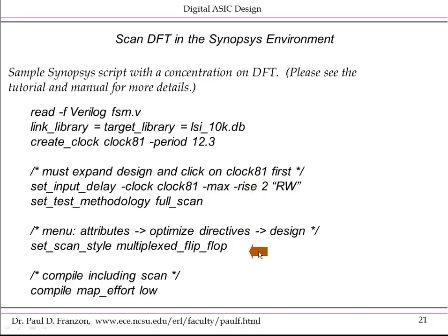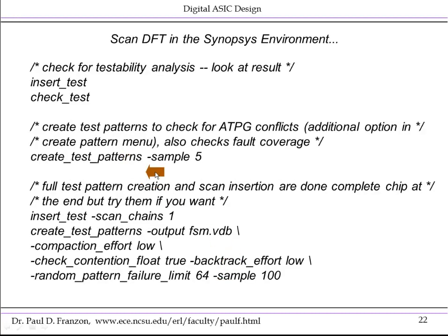We set the style of the full scan register, multiplex flip-flop. We then do a simple compile so that it actually uses these scan registers. Then we have insert test and check test. That actually checks for testability analysis of the chip. There's unlikely to be any problems that come up here unless you have some very unusual circuitry, but this is